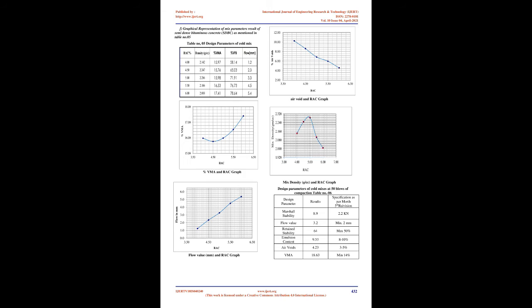B. Dense graded cold mixes, SDBC. As per the adopted design procedure, samples of aggregates, filler, and emulsion SS1 taken for analysis were produced by Marshall compaction. For suitability design of mix, samples taken from different sources to determine conformity testing, their testing parameters, results, and specifications are shown in Table 02 and 03 respectively. The optimum composition found based on initial residual asphalt content, IRAC, by arbitrary value and by empirical formula is shown in Table 05. Table 05: Optimum compositions of dense graded cold mixes.